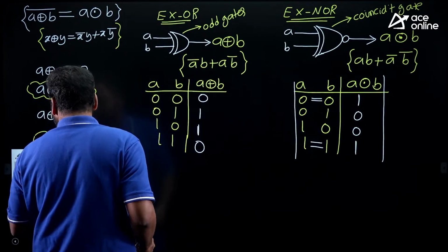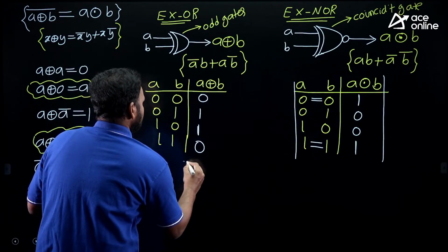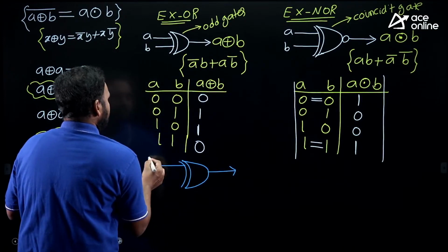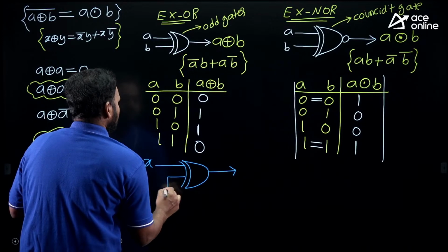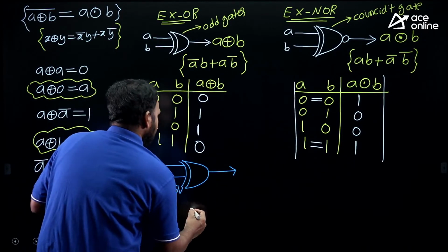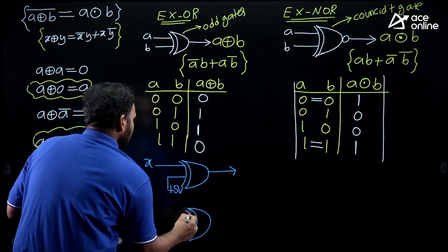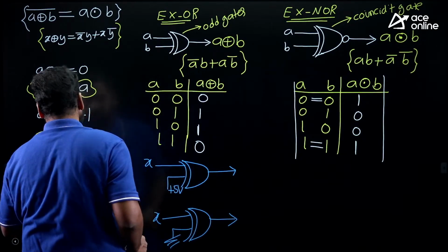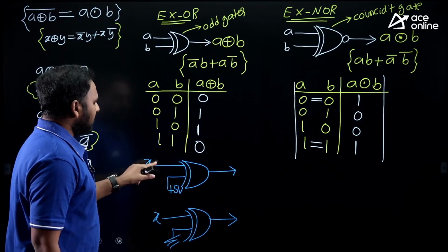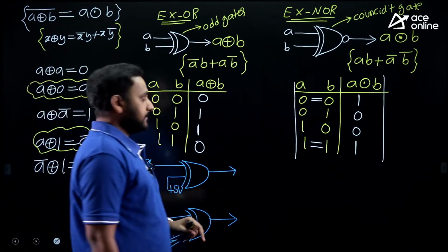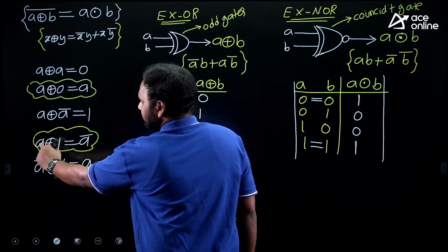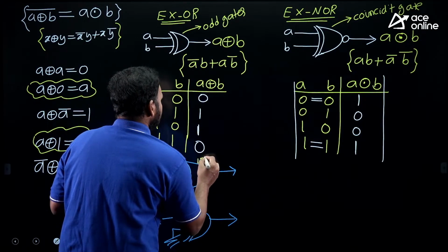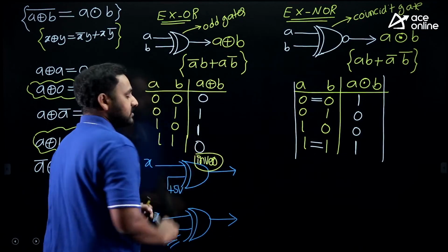They are giving the circuits like this and they are asking the name of the circuit. This is an XOR gate with the input something like X, and one input is connecting to plus 5 volts. This is also an XOR gate, giving some input X, another input is connecting to ground, and they are asking the function of the element. X or A or Y, whatever, XOR 5 volts means logic 1. If one input is 1, another input A, what did you get at the output? A bar. In this case, XOR gate is acting as a NOT gate or inverter.